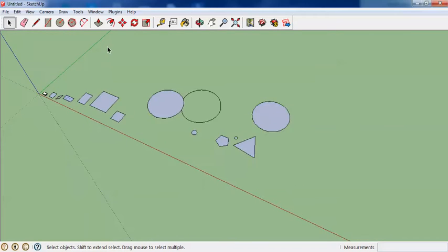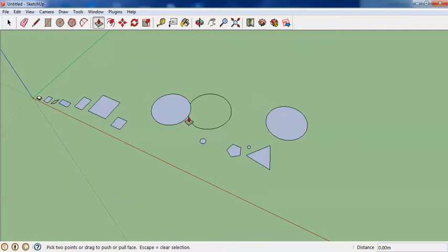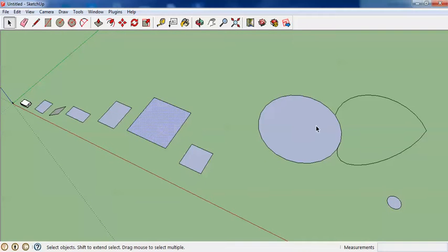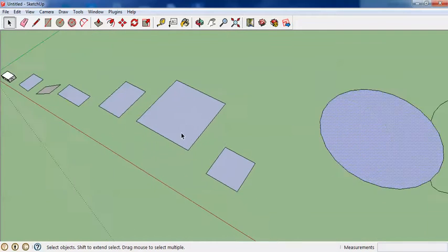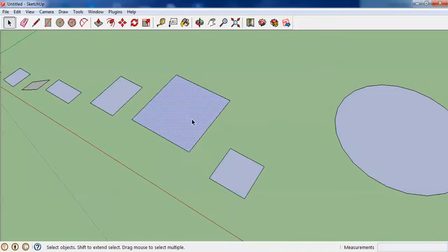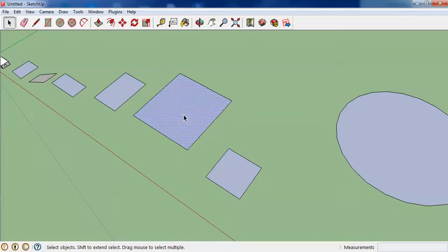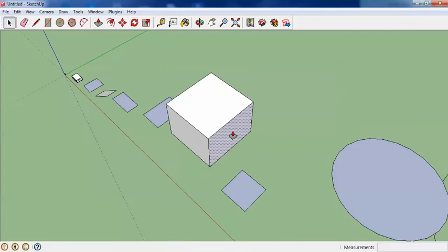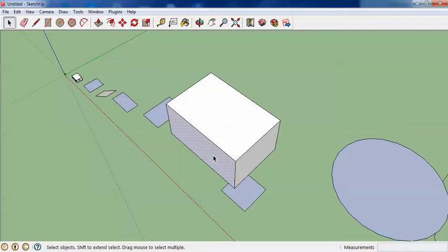The next important tool is the push and pull tool. The push and pull tool only works on this plane surface, and these dotted points that you see over here are the representation of the plane, and you can push or pull these dotted planes in any dimension in the 3 dimensions. Anywhere you like, you select the plane and then you pull.